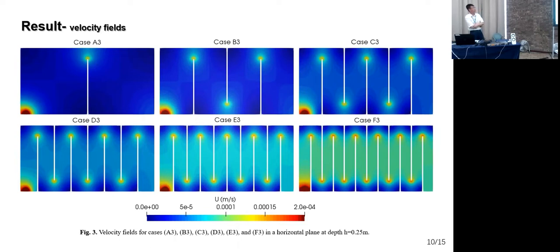It can be clearly seen that the cross-sectional velocity noticeably increased as the baffle amount increased. So in conclusion, the baffle amount has a significant effect on the cross-sectional velocity and is conducive to reducing the dead space.